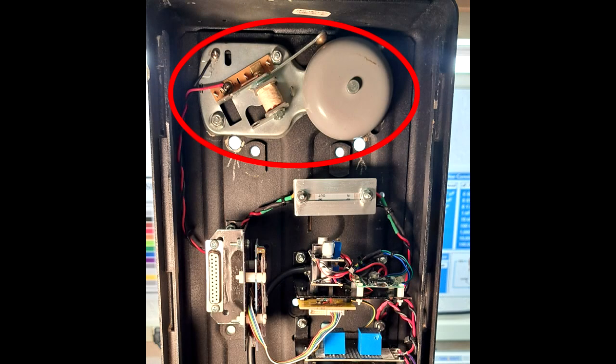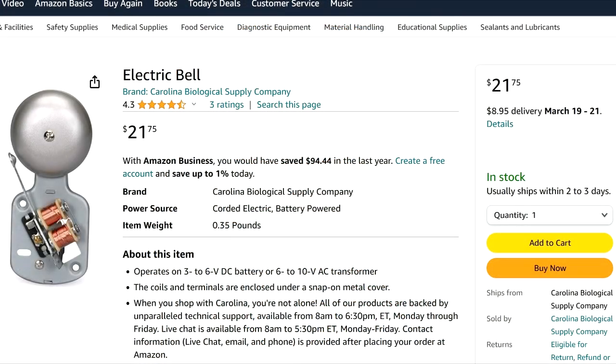In this case, a bell was also installed and connected to the second relay mentioned earlier. This adds a surprising and welcome phone ring when the door is opened. It is optional, but it is a nice added feature. The bell, also on Amazon, is rated at 6 volts. It should not be forced to operate at 12 volts like the latch.